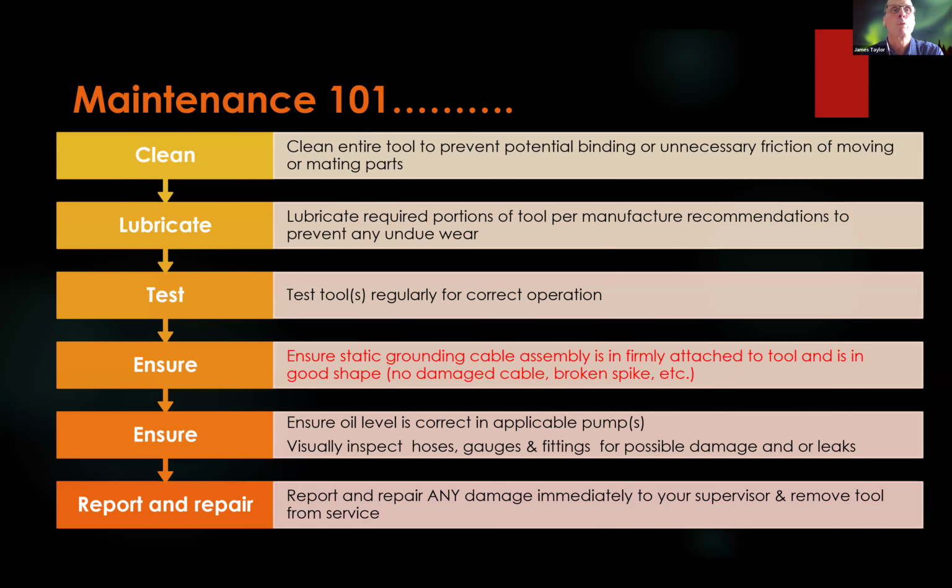Again, this goes to any squeeze-off tool, not just ours. We want to make sure we clean the entire tool, prevent any potential binding, unnecessary friction, moving parts. We want to clean them all, lubricate them as well, per manufacturer's instructions, for any undue wear. We want to test the tools regularly too for correct operation. That comes back to what I talked about at the beginning, where rain day, nothing's happening. Grab a stick of pipe out of the dumpster, test that tool, make sure it works, make sure you're familiar with it.